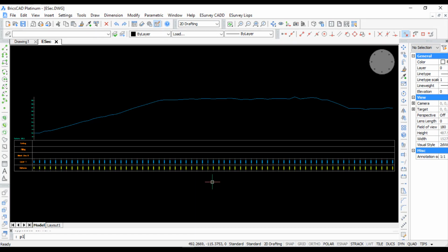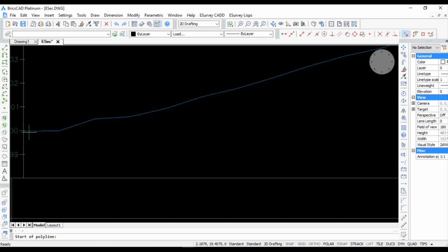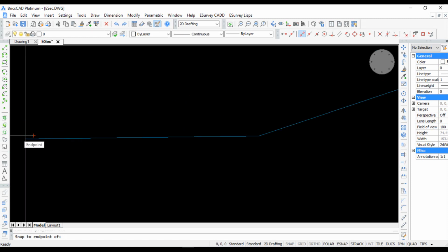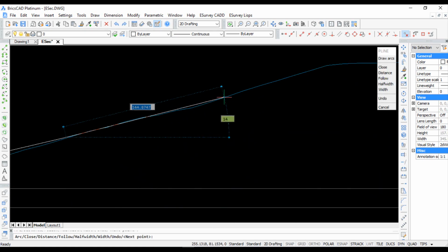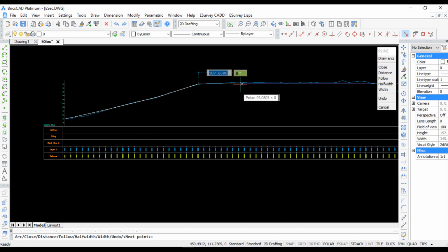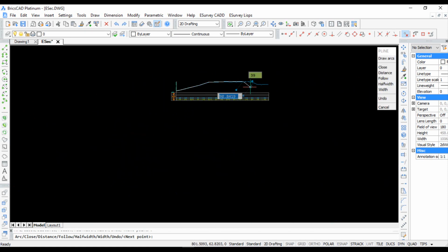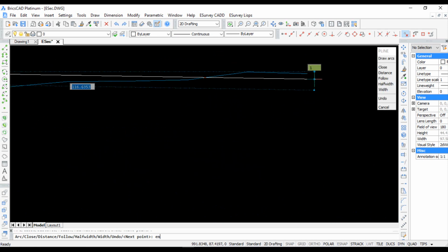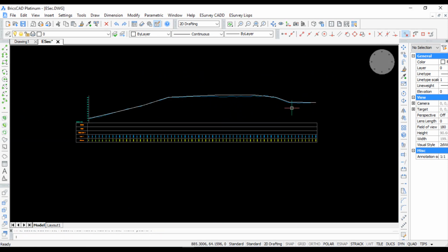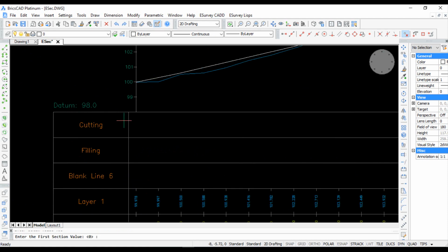Traditional method of designing vertical profile and its limitations. It is required to understand that the methods adopted to design the vertical profile with PCC can vary from person to person. The experience of the designer plays a vital role. The general and most appropriate method of designing such profiles is to design the tangents along with curves and constantly check the design so that it is optimal and as per the requirements. This can vary from zero cutting profile design to cutting of local stretches to reduce the PCC quantity. Though cutting of the existing crust is not advisable, in some projects it is done invariably to reduce the cost of PCC.